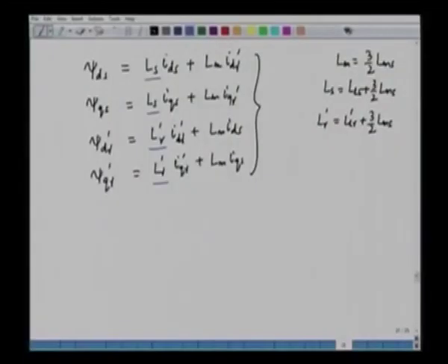We show them because to reconstruct back the ABC equations, if you want to transform id iq into ABC, you have to take help of the zero sequence component. The zero sequence component, although it does not take part in torque production, will be helpful in calculating back the ABC variables.